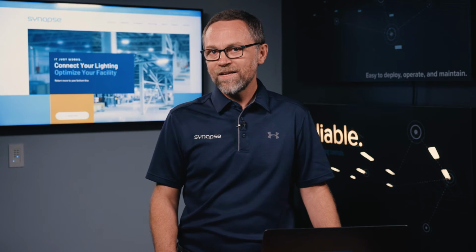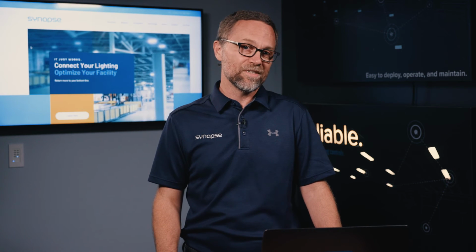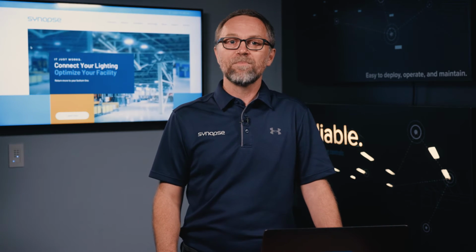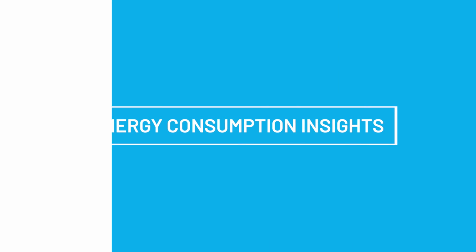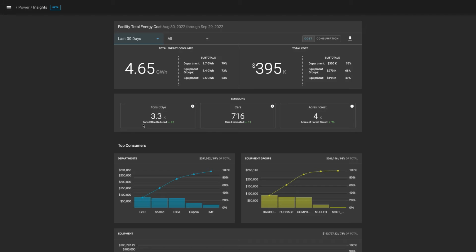In order to find places where energy waste is occurring, we want to track the flow of energy through the facility. SimplySnap can monitor the mains coming into the plant, submeter the departments, and monitor the power consumption of individual pieces of equipment. Let's take a look and see how you can do that. From the portal, I'm going to click on Energy Consumption. The first thing you'll see is the roll-up of total energy consumed across the monitored areas and how much it has cost you over the past month.